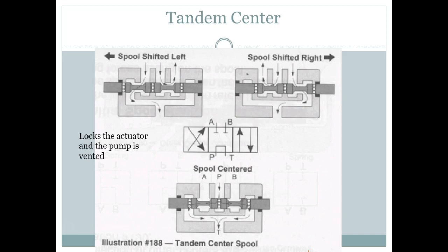In industrial applications, very seldom would you see water. You'd see oils, mineral oils. Most of the time now we use mineral oils. We used to use all different types of oils. This was the problem we had with our Rexroth system. When it came time to change it, we would have to have a hazmat crew come in to change the oil in there. Oh, mineral oil? No, it wasn't mineral oil. It was rather hydraulic fluid. That was before they started going back to mineral oil.